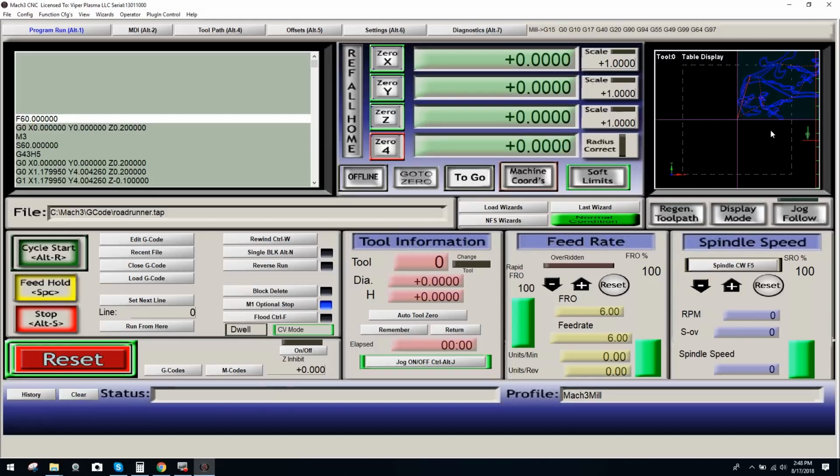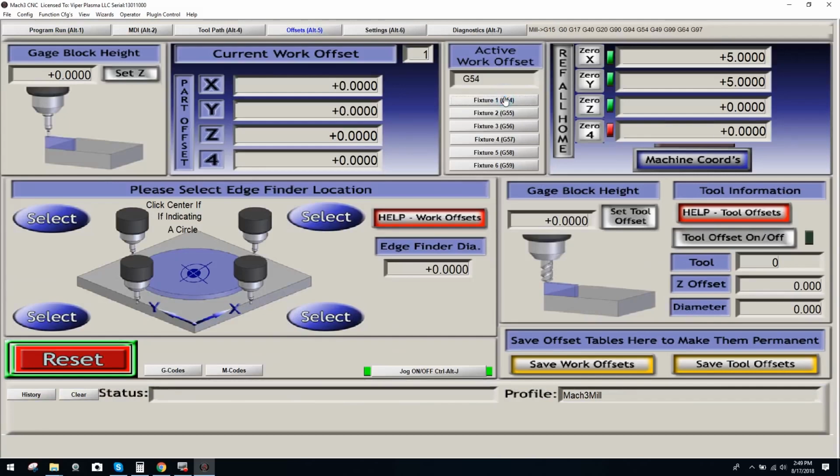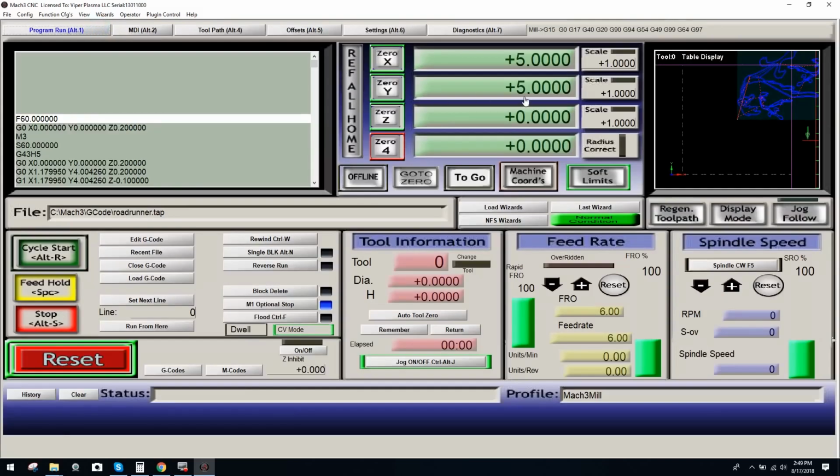Overall, though, another thing you may encounter, and this is something I want to show you guys. I'm going to go back to G54 now. Once again, you're all the way at the top left corner because it's going to move everything down. Now when I go to 0, you're going to see it come down here again. You see our +5 because we changed G55 over. Always validate your offset over here.